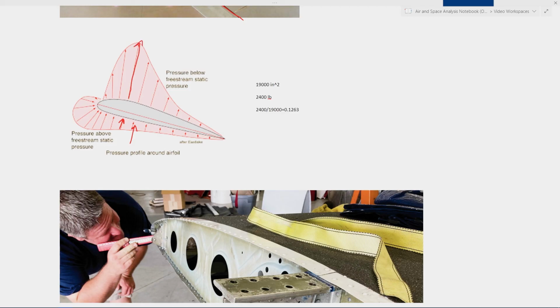So basically, this is how the wing is loaded, like pressure applied to the surface. So we want to approximate this in the model. Now we can approximate this kind of curve around the wing, but it's a little bit involved for this video, since we've already created the model and the mesh. I thought I would keep it a little bit more simplistic as far as pressure, and then we can revisit creating something that looks just like this in the future.